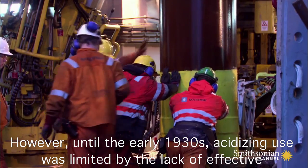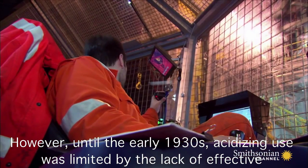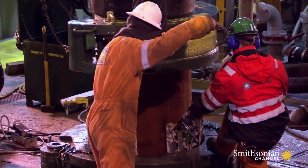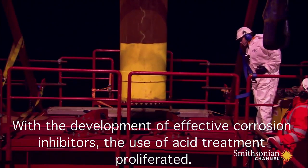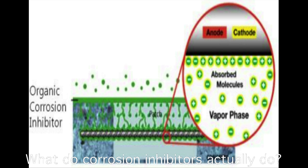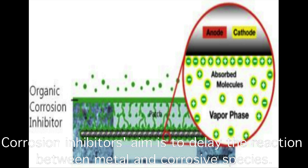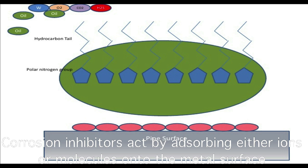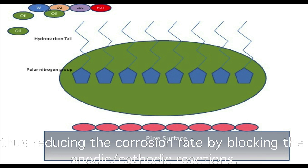However, until the early 1930s, acidizing use was limited by the lack of effective acid corrosion inhibitors to protect the steel tubulars in the wells. With the development of effective corrosion inhibitors, the use of acid treatment proliferated. What do corrosion inhibitors actually do? Corrosion inhibitors aim to delay the reaction between metal and corrosive species. Corrosion inhibitors act by adsorbing either ions or molecules onto the metal surface, thus reducing the corrosion rate by blocking the anodic or cathodic reactions.